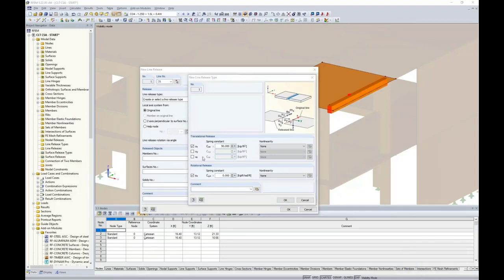So what we want to do here is to also show you that nonlinearities are available. What we can do with nonlinearities, this might be applicable with the Z direction. So for example, if we have a downward deflection here of our panel onto our beam, we can set this so that it is fixed if a positive VZ. So if we have a downward deflection here in the VZ direction, then we'll see this connection fully fixed. Now, in turn, if we have an upward deflection of the panel, then we would see a fully released connection between both our beam and our panel.